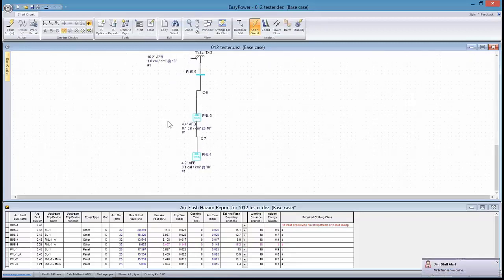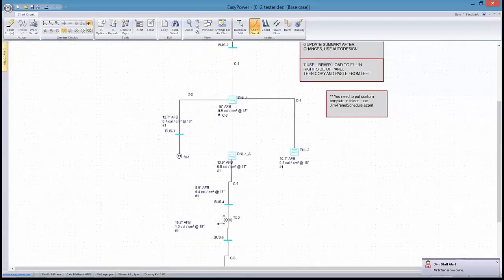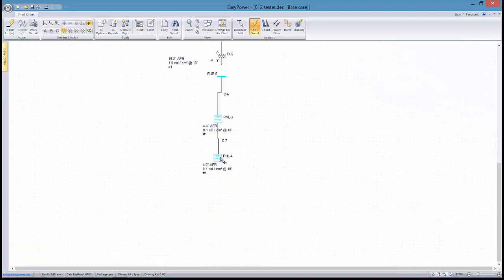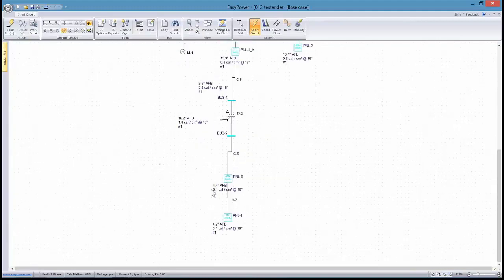Okay, so what have we done so far? We've populated breakers and panels with copy and paste, with subsystems, with raw data or bare entry. We've entered subpanels. We've conducted arc flash studies on single phase, albeit a little bit conservative. It's still within the parameters of safety, and I think we've done a pretty good job of covering the subject. So that's going to conclude today's schedule.